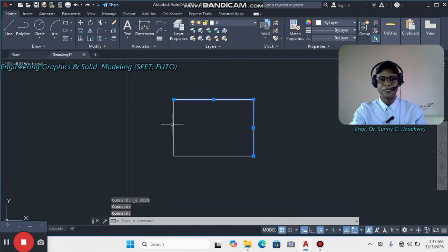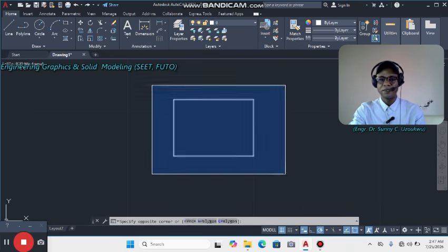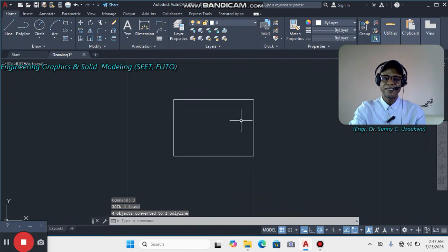Now when it's not joined, as you can see, as I'm clicking it, it's selecting differently. So that is different. There are some commands it can execute when they operate as separate elements. That is why it's very good, if you're going through this procedure, at the end of the day to make it a single element by selecting everything, then type J. J is the shortcut for join, enter, and that gives you a single element.